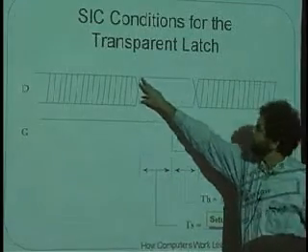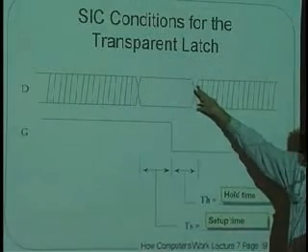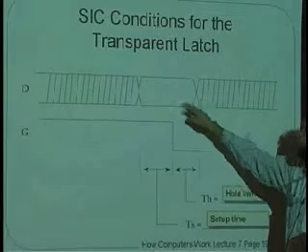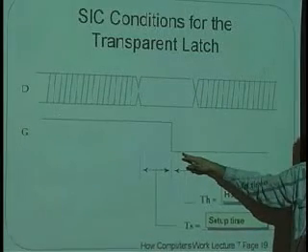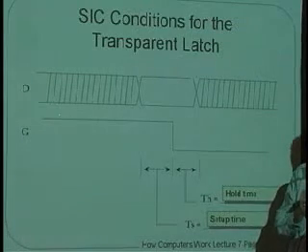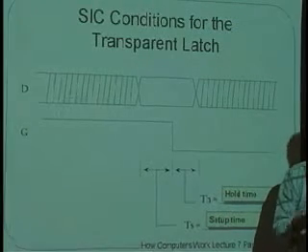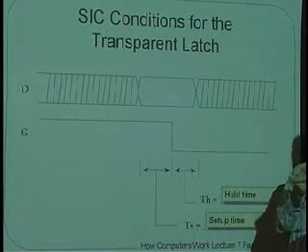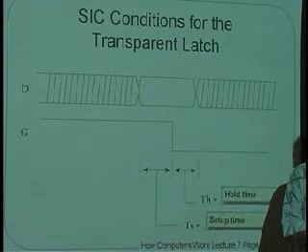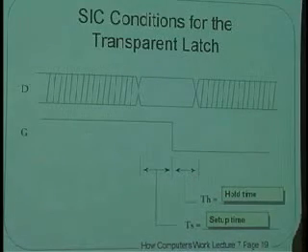And so we'll establish the setup time beforehand and the hold time after and say that this guarantees that only one input has changed at a time on that circuit, and thus the circuit is hazard-free, and thus it will be able to hold on to the value properly. And there will be no glitches trying to go around and around the loop, but rather just a constant value going around and around the loop. And so this is how we're going to build this latch.